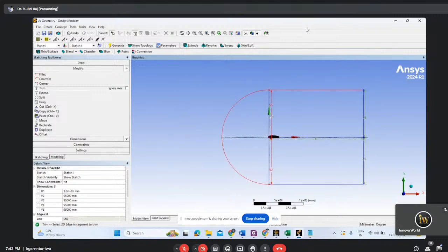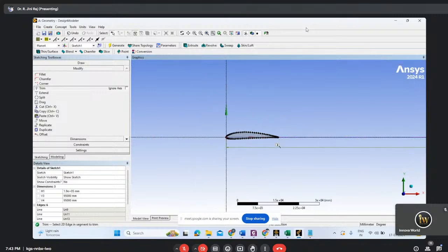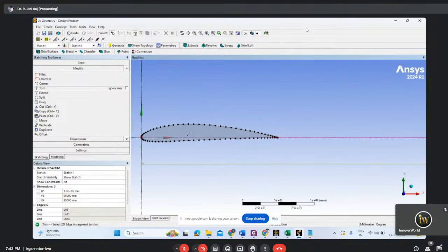And here also two types of mesh we can do. One, if you want to go for structured mesh, we need to make the control volume accordingly. Or if you want to make unstructured, then in different control volume, so accordingly we have to make.